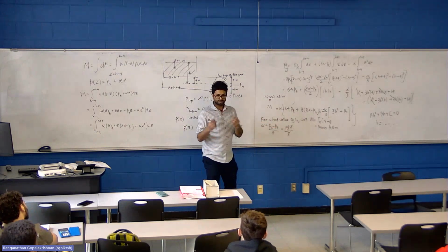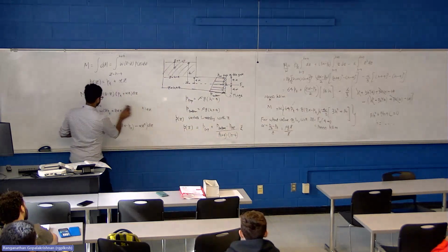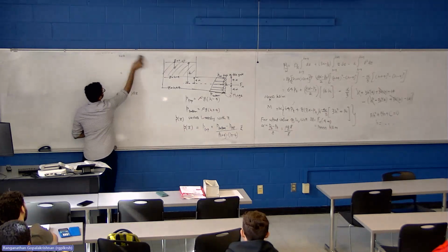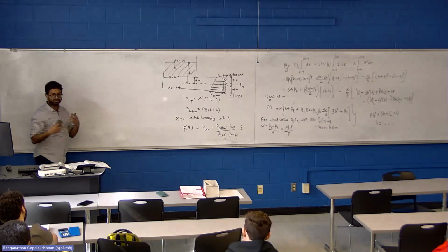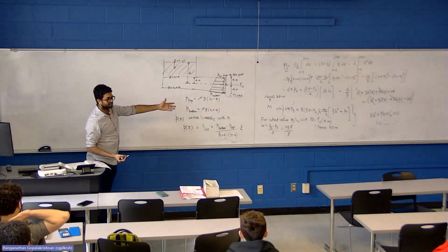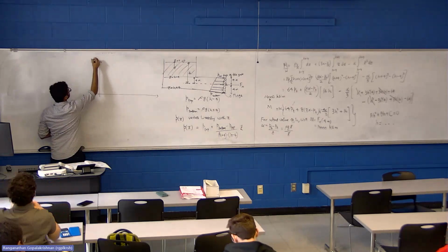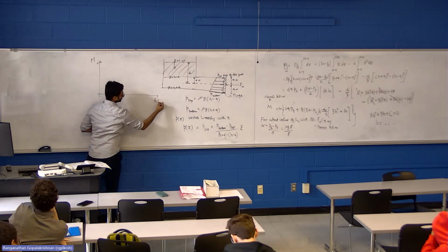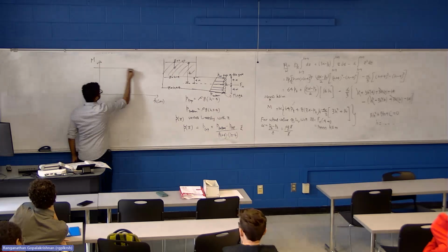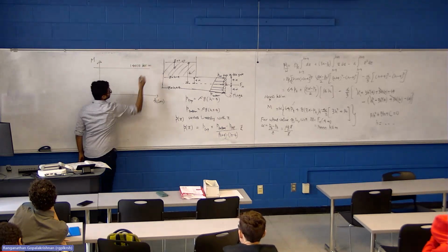Here is what I suggest you do, which will give you some useful information. The moment that constrains your design is how much? 14,000 kilonewton meters, right? So if we plot the quantity M as a function of H, the value that you are targeting is at a certain level, 14,000 kilonewton meter.